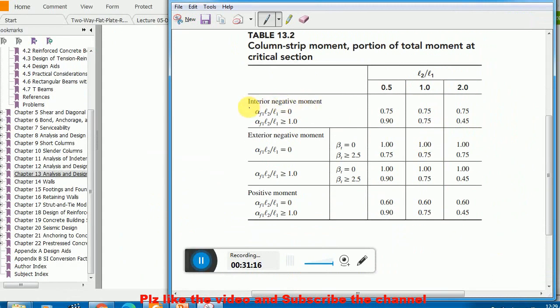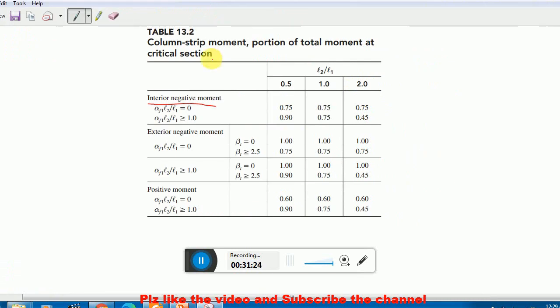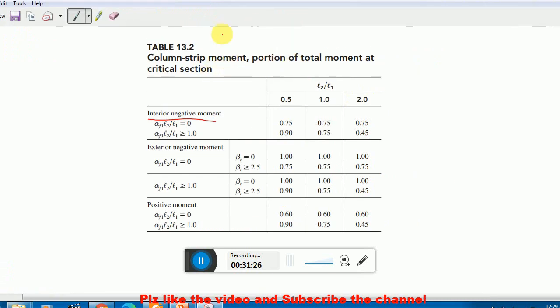Now see, for the interior negative moment we got the 0.81 coefficient. We got that value from the graphs, but how do we get that value from this table? The ratio in our case, you have to write down 0.5 here and 1 here, and the 0.8 value will be in between these two values.